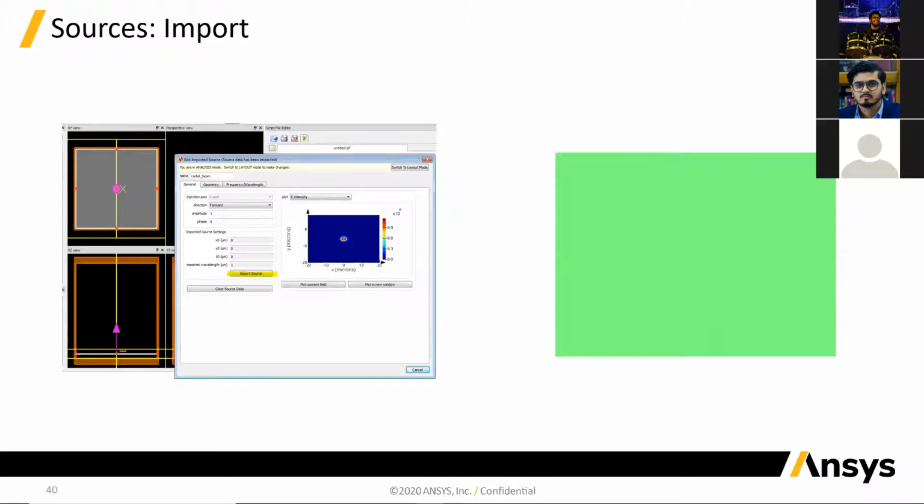In these cases, what you can do is, in your propagation direction, break the simulation into multiple parts. You inject light from the beginning. Halfway into your geometry, you capture the electric field using a monitor. And then you run a second simulation where you use that information from the monitor as a source. You load that data into your import source, inject the light into the second half of your geometry, and then see how light propagates through the second half. So that would be a simple use case.